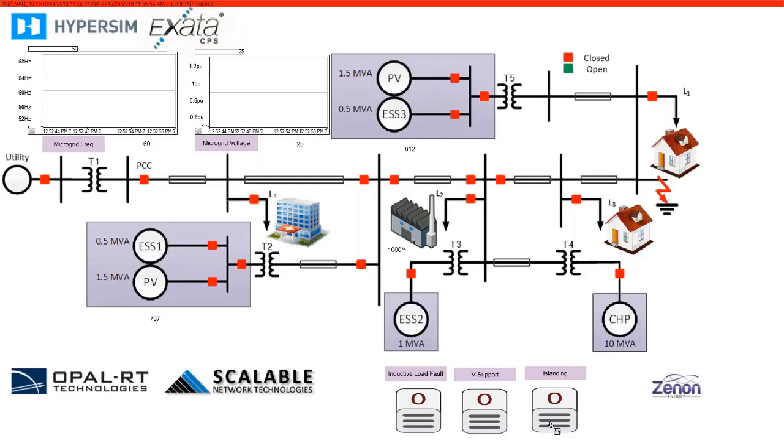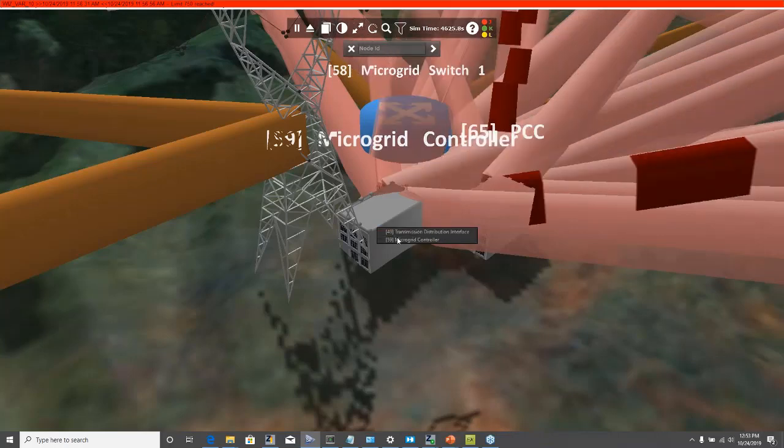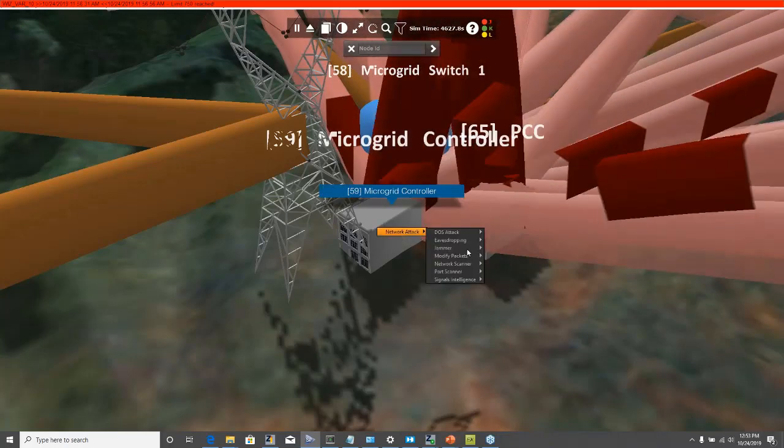And when I click on islanding the grid, you'll see here that there's a long delay, the frequency drops below the threshold that has been set. The voltage also drops much lower. So you can easily extrapolate to potential damage that can happen to the grid, backup protection kicking in. But obviously, this has a serious impact on the microgrid. We're going to go to our second scenario, but first I'll just stop this first attack here.